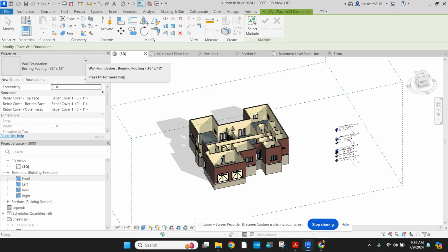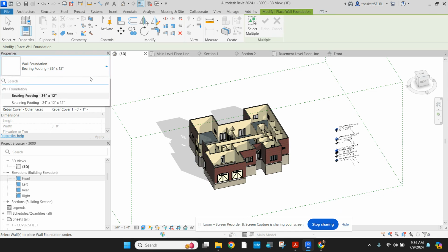Every time. Most of the time on a house this size, where it's 3,000 square feet, you're going to get something closer to, probably on this one with brick, it's pretty close to that. Might be only 10 inches thick instead of 12, and it might be 18 inches instead of 24. It could even be down to 12 depending on the type of soil that you have.